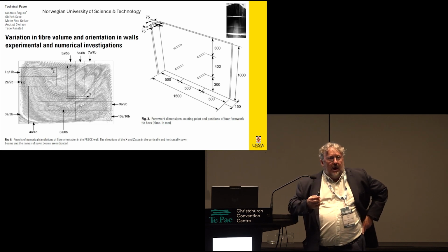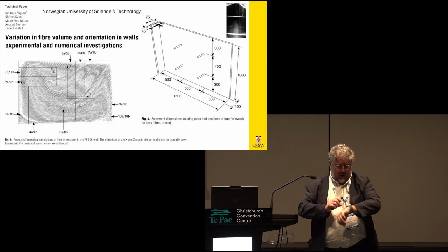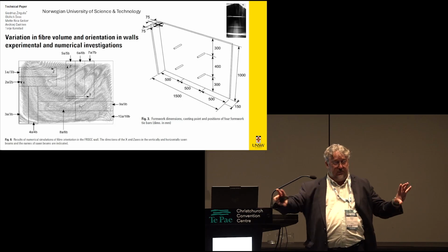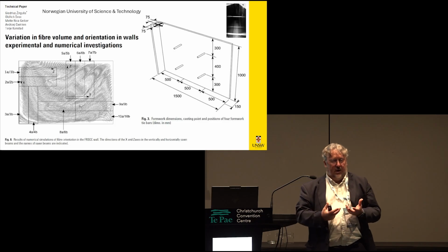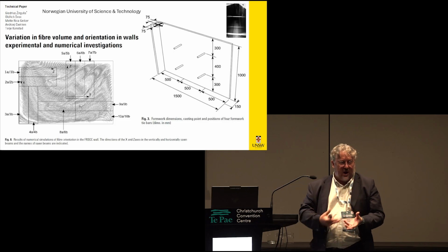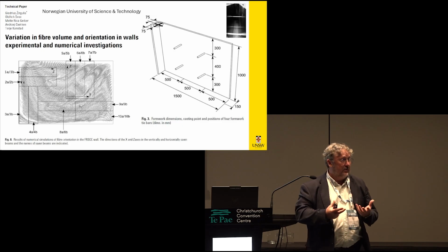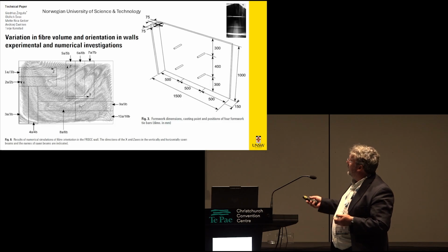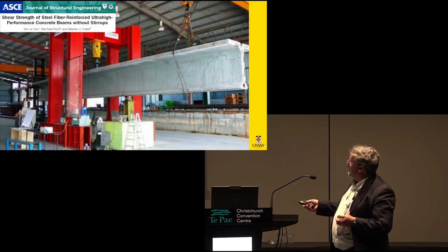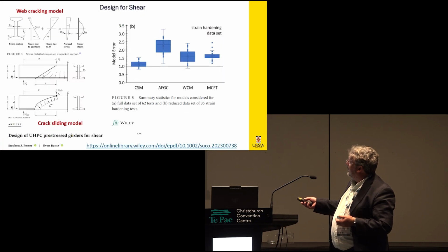So unlike steel reinforced concrete construction, where we have a lot of flexibility in placing the steel, we know it's there, we tie it down, we see it. With fibres, the construction process in itself is very important to make sure we get fibres aligned. All the codes have models for that, and again, just showing some large-scale testing. I won't go through these for time.